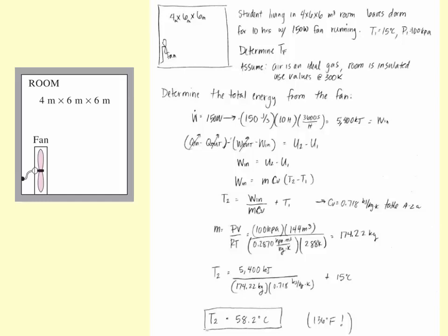It's equal to U sub F when we are a saturated liquid. And it's equal to U sub G when we are a saturated vapor. And then somewhere in between, you need to know the quality to find what U is. Yes. Okay, so in this case, that's not even applicable because we're a gas.